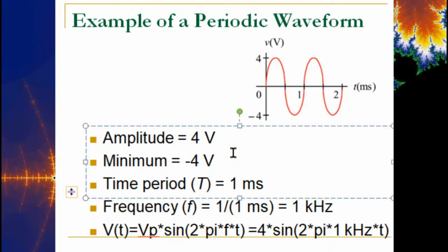Well, let's do something with that real quick. How about, what is the voltage at t equals, let's pick one, right? Let's just look at this for a second. Half a millisecond would be right here. That's 0. Anything from 0 to half a millisecond, or 500 microseconds, is going to be positive voltage. Anything from 500 microseconds to 1 millisecond should be negative voltage. So just pick some value in between and see if you get the calculation correct.